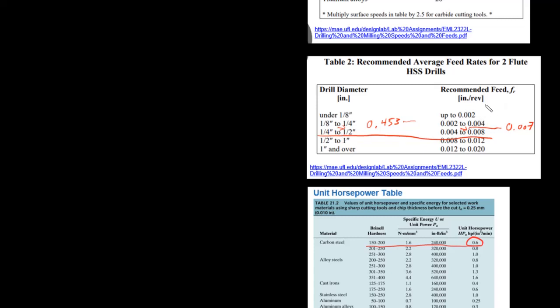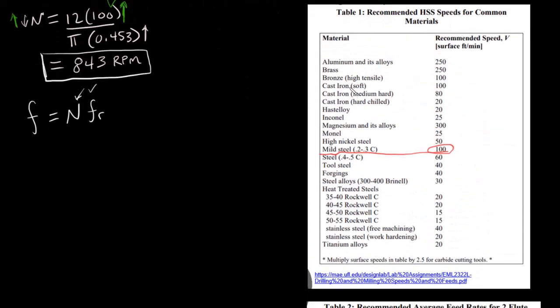What gives us a clue is that, if you look at other tables, there's lots and lots of tables for materials and speed, surface speed, that they'll give a range, so maybe 200 to 400 for high-speed steel cutting tools, all of these would be numbers in between.